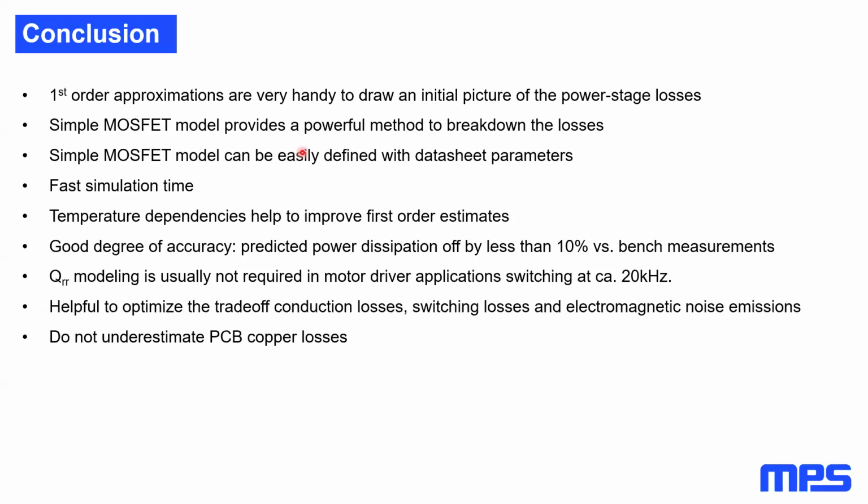Other people may have the motor 0.5 meter, 1 meter, 2 meters, 3 meters distant from the control unit. And we have seen people in these cases that may have an interest in going as slow as several microseconds of rise and fall times, whereas when things are very compact and especially when motor power might be quite high, we may see people being as aggressive as down to the hundreds of nanosecond range.